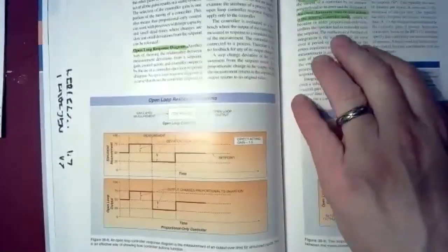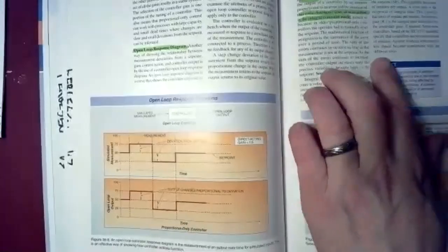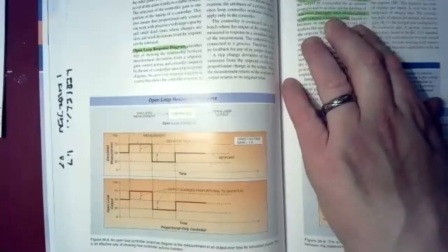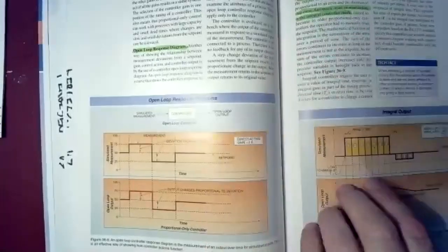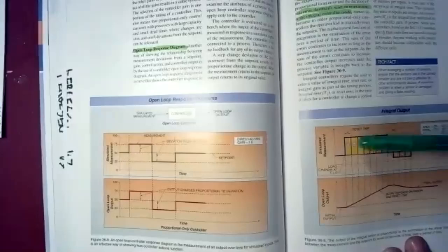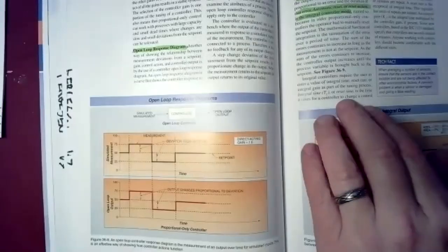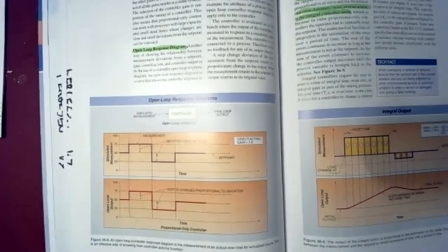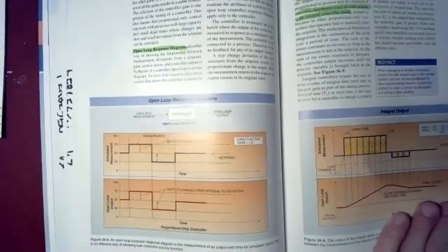So if I've been off temperature for 5 minutes, my temperature might be a simple gain. But then if I've been off temperature for 20 minutes, then that gain increases. So each period of time that you're off temperature, you add to the change in your controlled variable. So it will keep cracking open that heat until it sees a response to your temperature. So it's looking at the speed of change, not just the amount of error, but the speed in which you're responding to your changes in your control temperature.